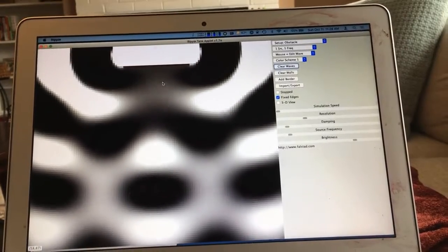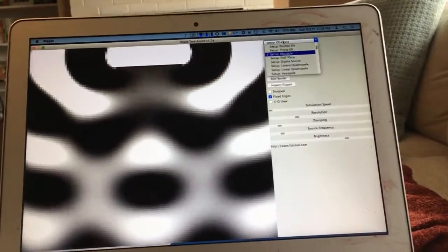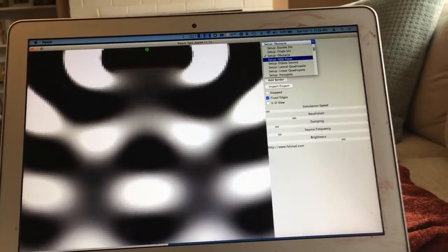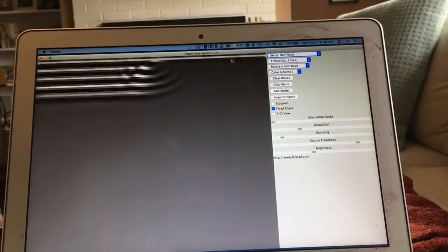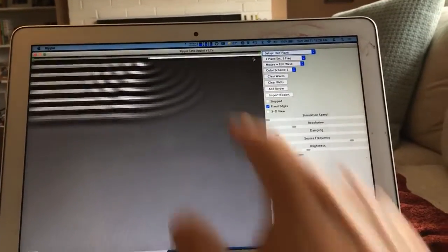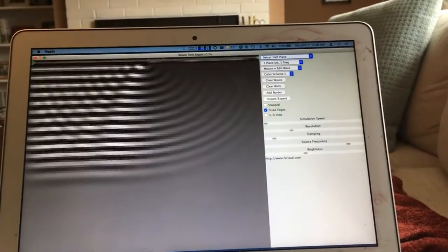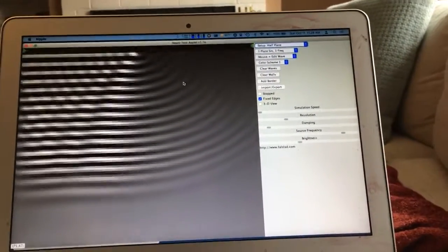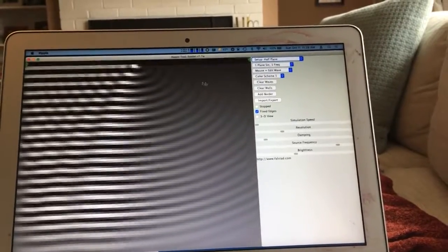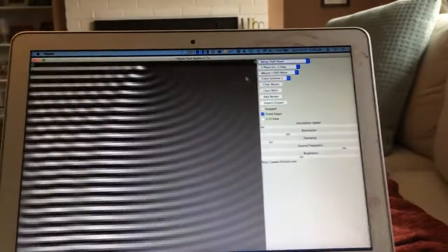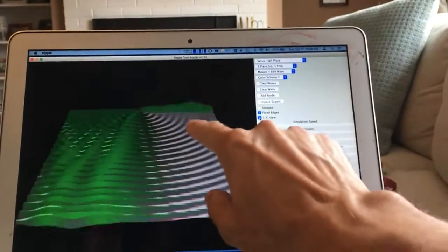The next one we want to do is half plane, which I guess even more resembles a highway noise barrier. Let's see what half plane looks like. Okay, so here is my noise barrier, this red line up here, and then I've got my source of highway noise over here. At this frequency, this barrier is much, much larger than a wavelength, so I get a pretty good shadow zone over here, maybe where I want to build my house. So that's pretty good. It's pretty quiet over here.